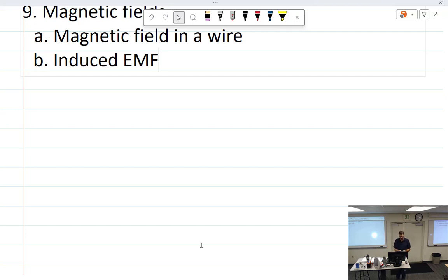So what's going to happen is in our secondary coil, because that's what it would be, the primary has the power, the secondary is not the power. We're going to have that magnetic field going across this constantly, and we'll have constant voltage out of this side because of the relative movement between everything. Every time it grows, it charges it. Every time it discharges, or goes down, it's going to follow it, doing the same thing on the other side. So it's 1-to-1? Oh, we'll talk about that next week. It's not. There's a ratio of how many turns on the primary versus turns on the secondary. That's next week's talk, the transformer.